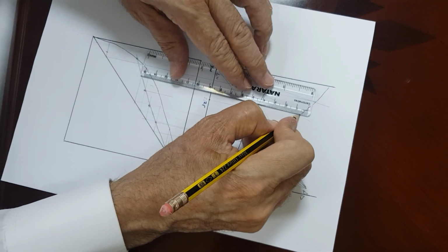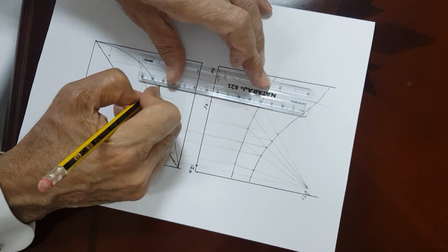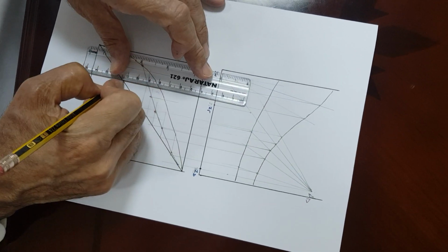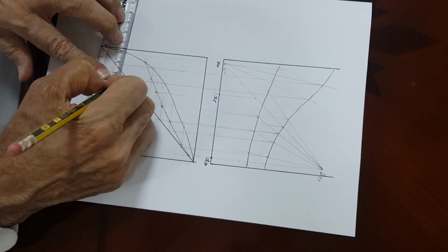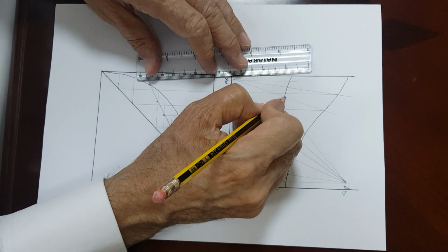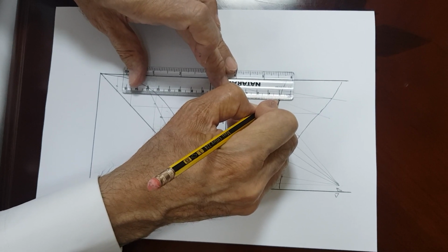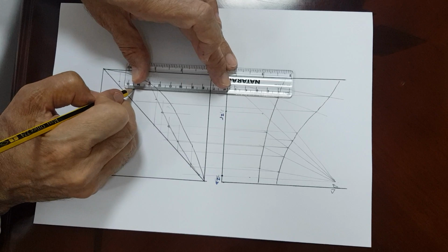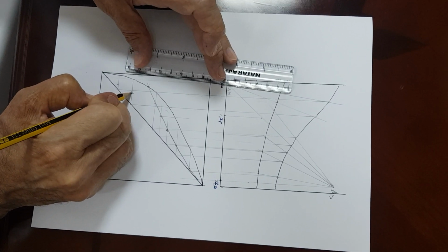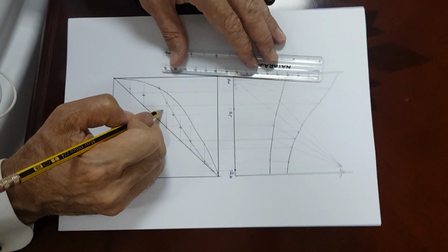And then you draw another random line, drop a vertical line, the 45-degree line, then a horizontal, and then another vertical line from the liquid enthalpy and down to here. So that gives you a second point. And you continue the process.